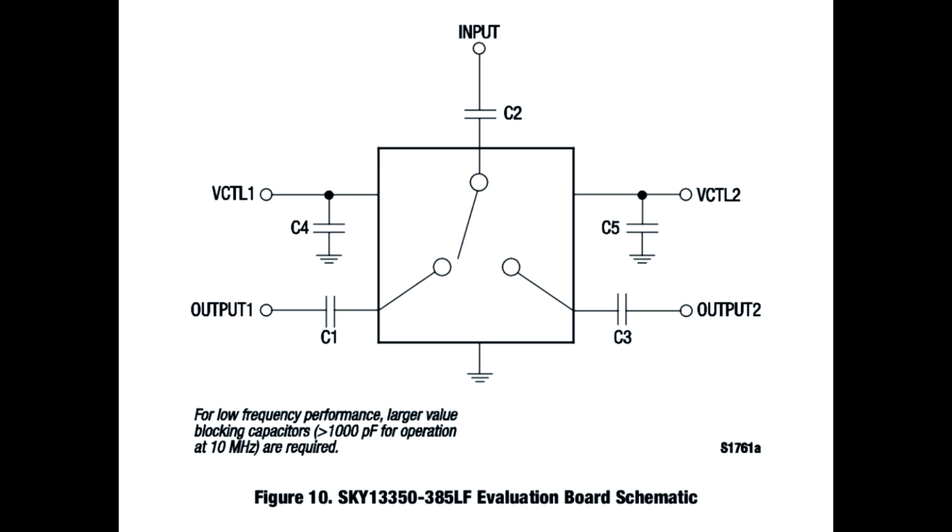But you can solder them. And this is one of the things, like when you get into RF, you just have to start to get used to doing 4-layer boards. You have to get used to using 0402s. You have to get used to using QFNs because those are the best components for the job. But you will get used to them. You can do them. You can drag solder QFNs.